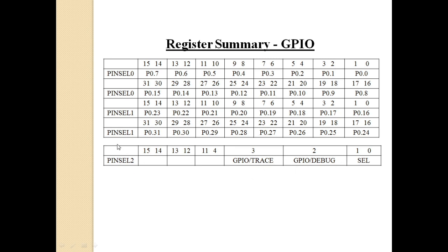So here I am using the PINSEL2 register. That functionality I have specified. If you are configuring pin number 2, bit number 2, you can configure it as GPIO or debug port. If you are configuring bit number 3, you can configure it as GPIO or trace port. Right. So these are the steps involved in blinking an LED connected to GPIO port P1.16 to 31.